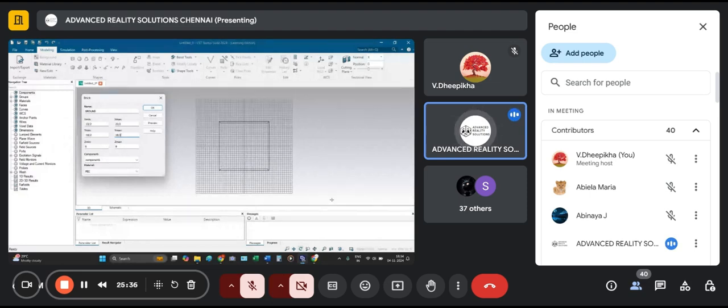So during that time, the design engineer will use copper material. Like for the ground layer, he will use copper. That is what we are going to mention. The common copper thickness value that is used in PCB prototyping is 0.035. So I will use the value here. The initial value is 0 from the ground layer level. Please understand this is the first layer. So it is going to be 0 and the maximum value is 0.035. This is a standard value.